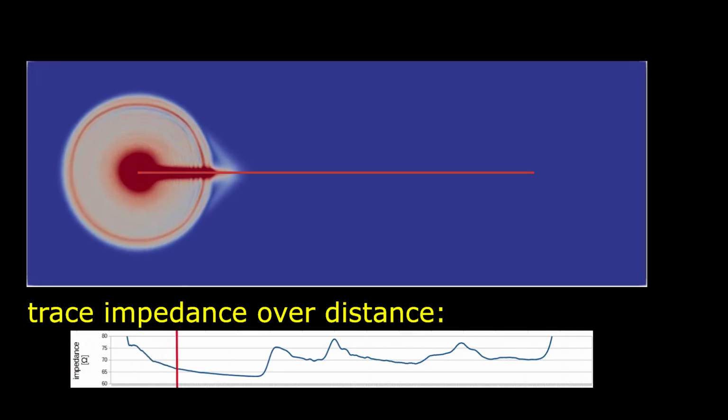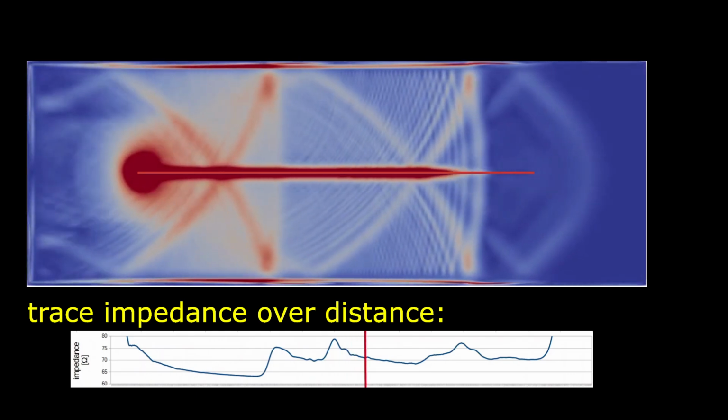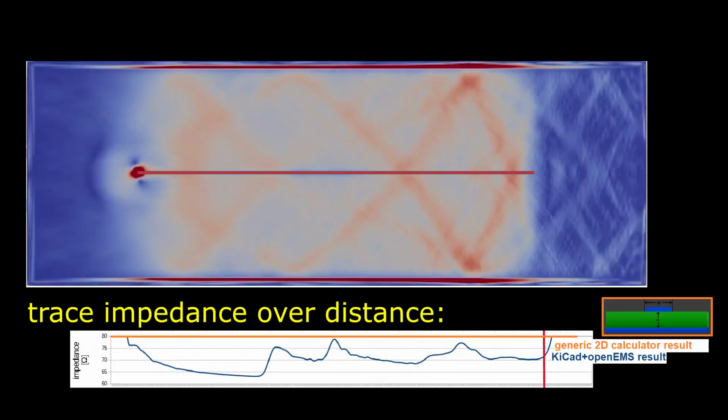In this video, I will show you how to simulate the impedance of a trace over its distance using the free tools KiCad and openEMS. Even for this completely straight trace, the full 3D simulation shows quite a bumpy impedance response due to the signal reflections from the PCB edges.